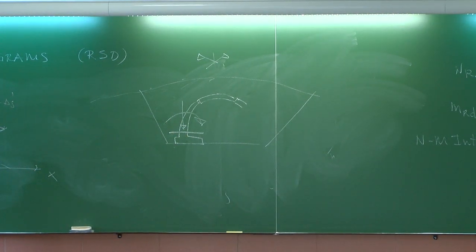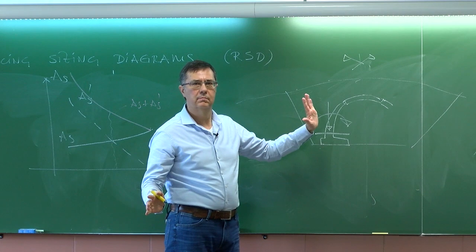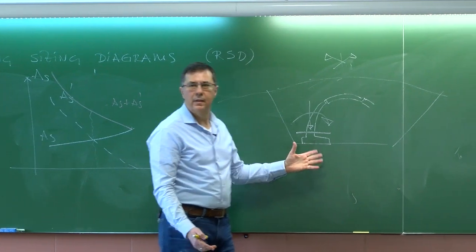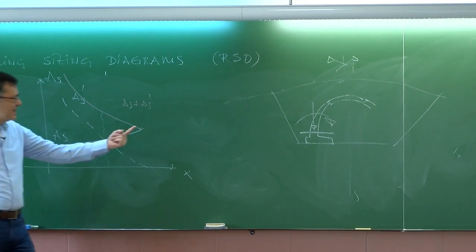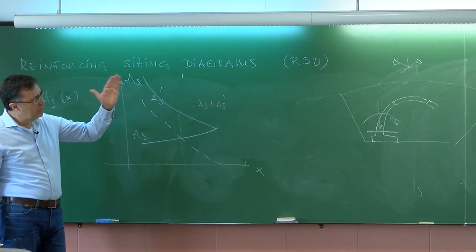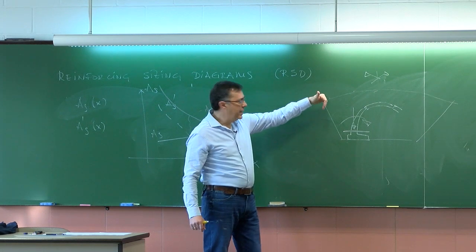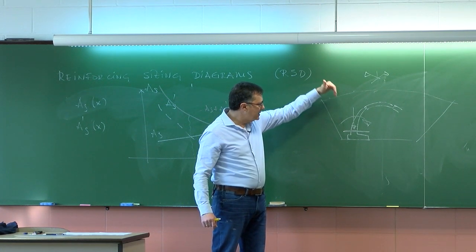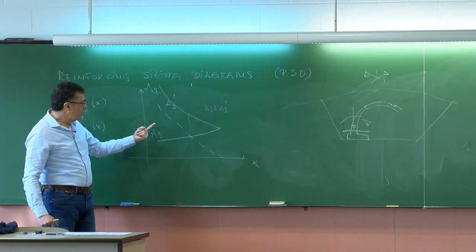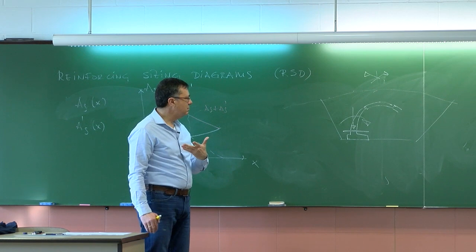Many of our colleagues will say, okay, big axial force, symmetrical reinforcement. I deal with this topic very often. So please, just use this. I know that we all love the PM interaction diagram, but for cases like this, where the worst case scenario is very clear and is likely just 1 or 2 or 3 pairs NM, do an RSD, and you can see where the minimum is. And we can save tons of steel.